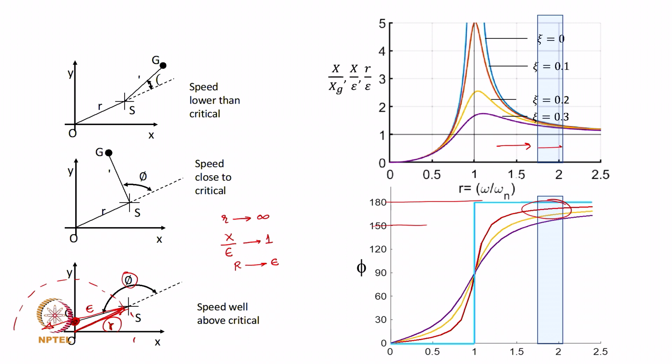So, what happens is that the rotor is actually whirling with the mass center close to the bearing axis, and so you basically have the entire vibration whirl motion with an amplitude close to unbalanced eccentricity. And it actually turns out that if you try to reduce the eccentricity value, your response amplitude becomes 0 or close to 0.